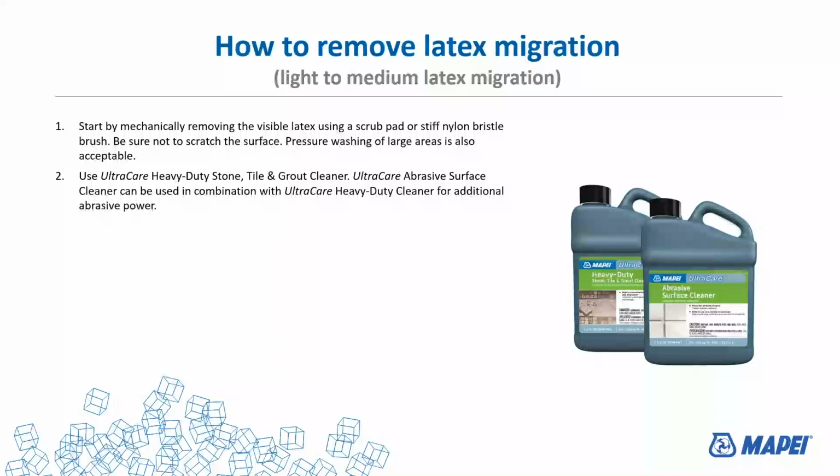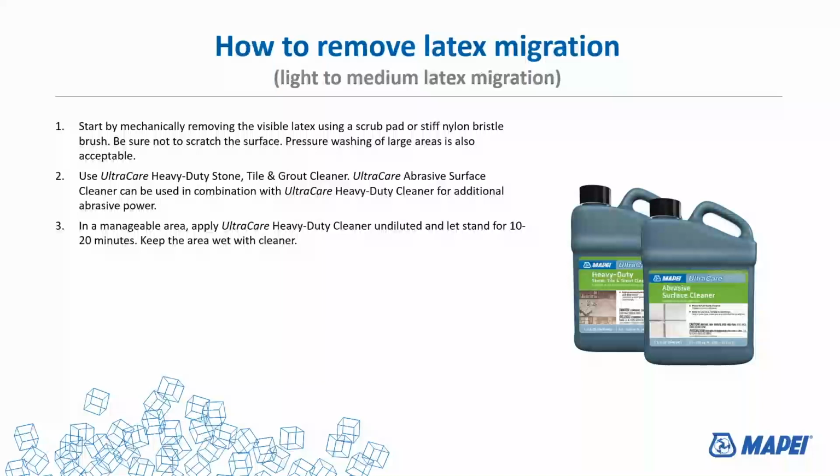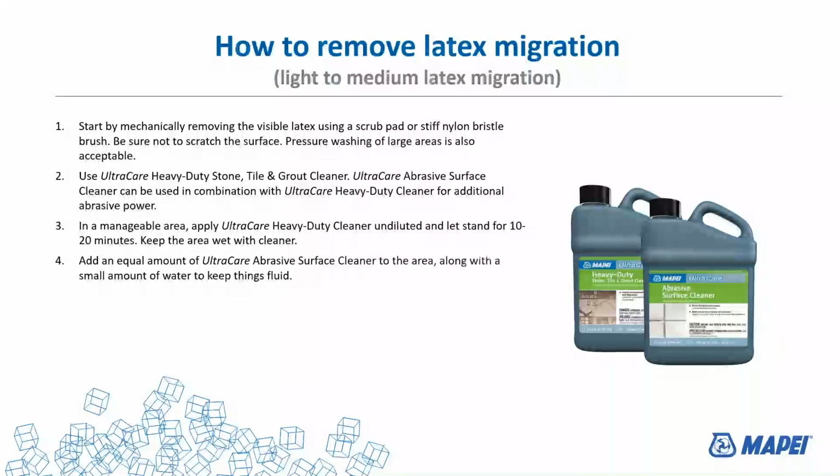You're going to let it sit for 10, 20 minutes, depending. I've never seen it take longer than 20 to actually work. You can add a little bit of water by using a spray bottle and mist it to keep it wet if you need to. And then you add the equal amount of abrasive on top, like I was mentioning, and then you scrub it, and you should get a pretty good result. If you get a 50% result, do it again. So it may take more than one scrubbing to do it the right way.